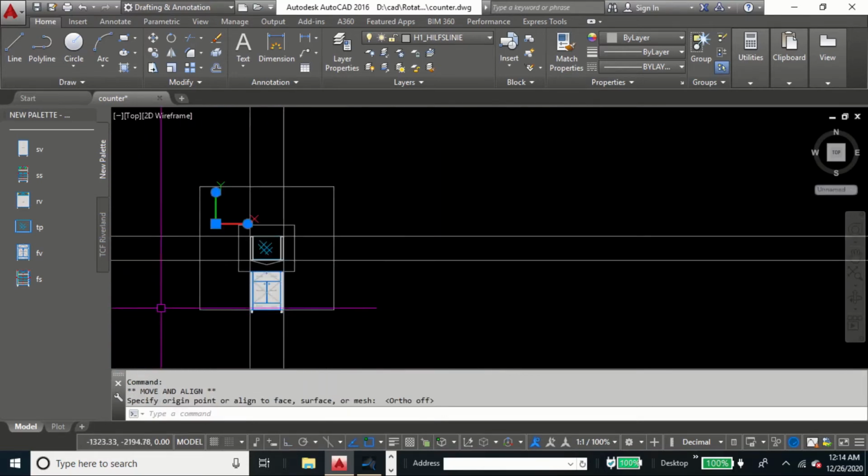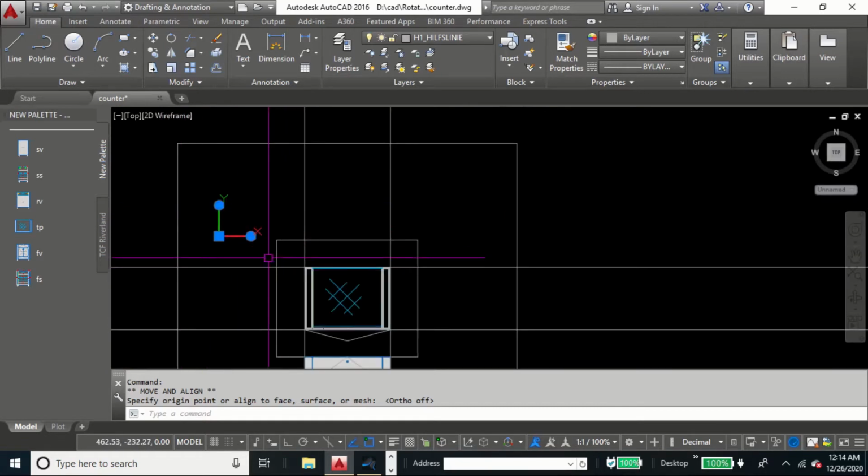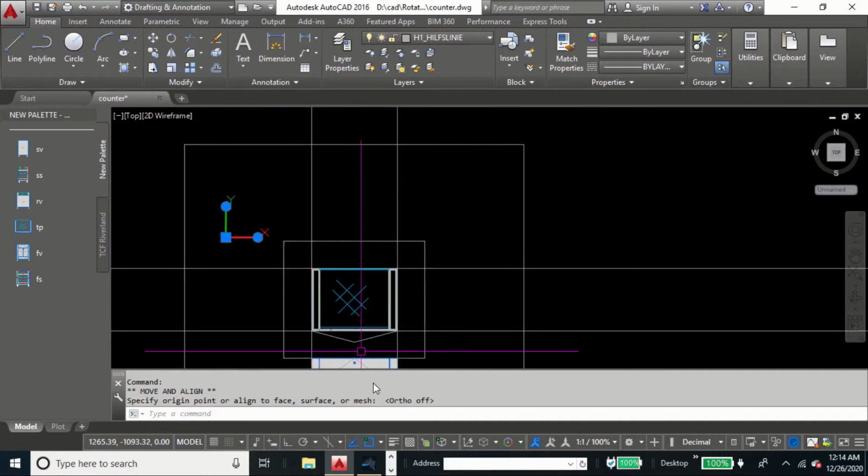So I just zoomed out so that the UCS icon is not residing on the lower left corner, where it is a bit difficult for me to select. Now once you do that, these are the two settings. Make the UCS selectable, then make it the origin point, so the icon is somewhere on the screen where you can conveniently select it.